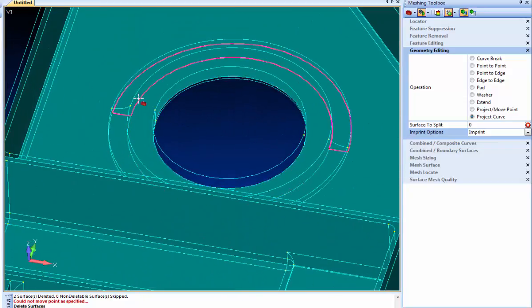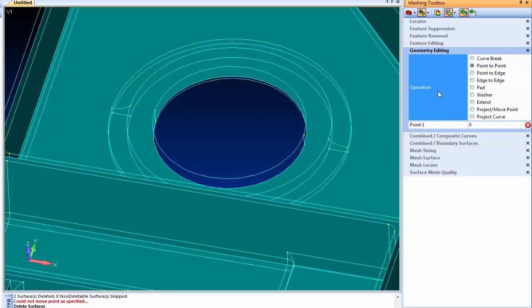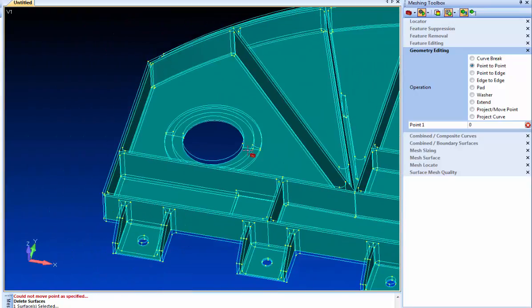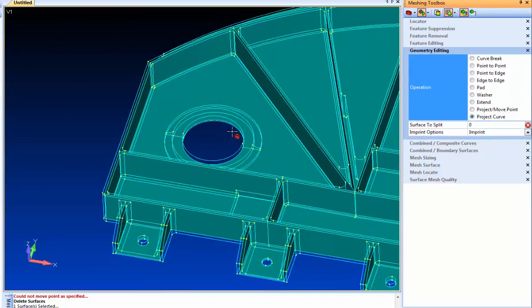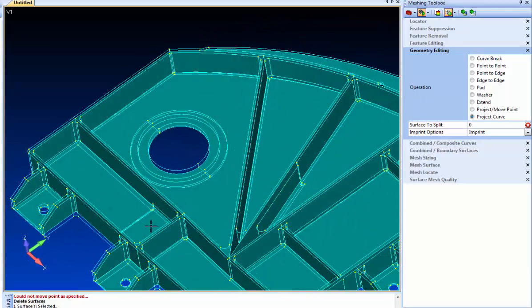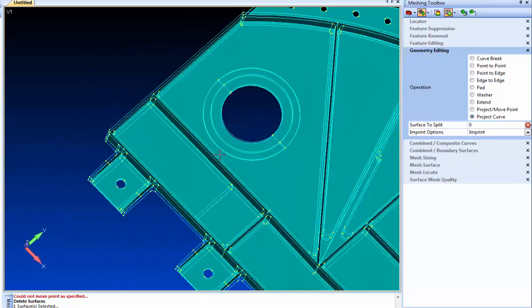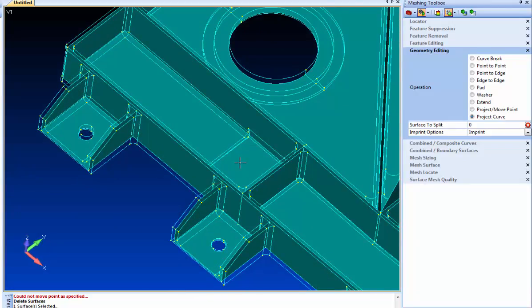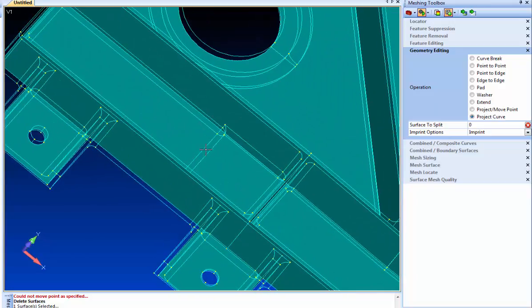And then when I really want to get into some map meshing, instead of having this circular annulus here, I'm going to use another split option we have in Femap and just split down in here. So now I'm going to be able to just play with the meshes later on. Now one other thing we need to do on this part, there are a couple of regions where there's thicker regions in these pockets that I definitely want to capture. So I need to kind of burn those splits in too into the mid surface.